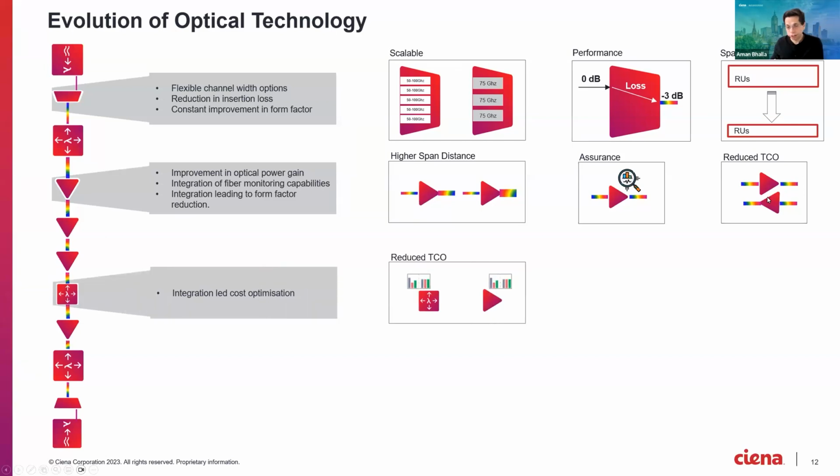Now, another thing we saw a few slides ago is that the ROADM component plays a part in equalizing the gain of wavelengths, basically bringing all of them to the same level so that they can traverse across a few kilometers or many kilometers and tolerate the discrepancies. But ROADM is definitely expensive.